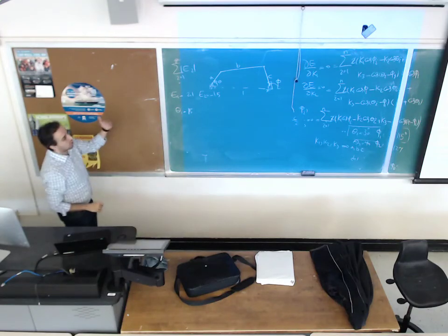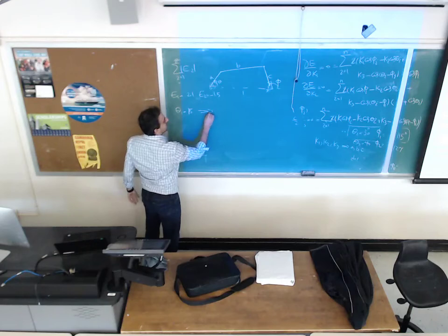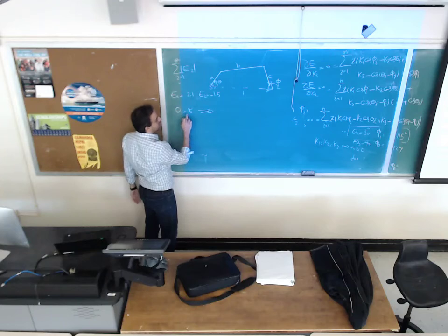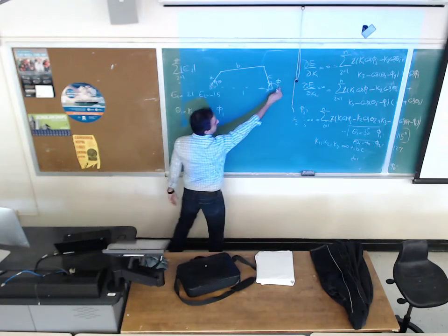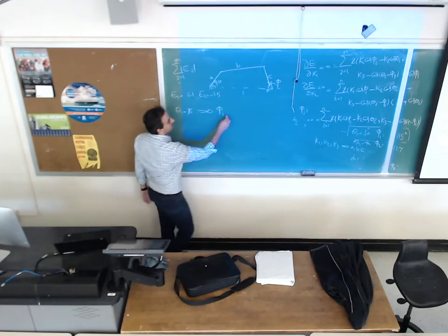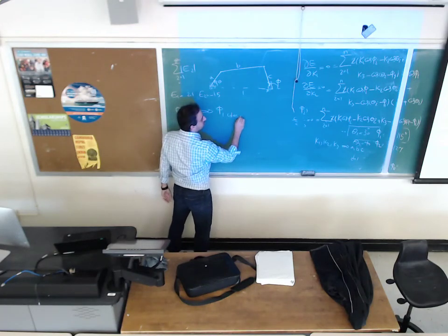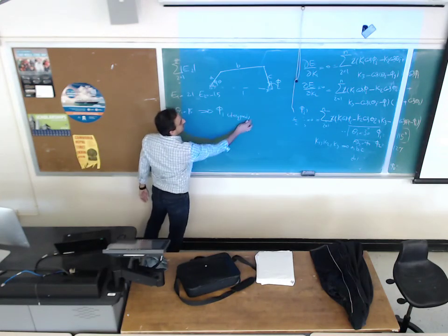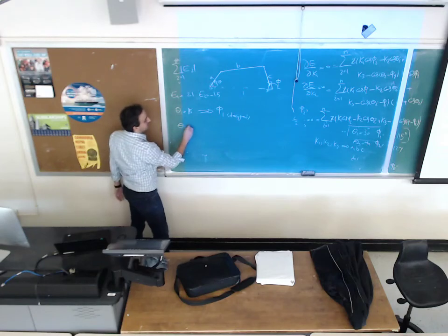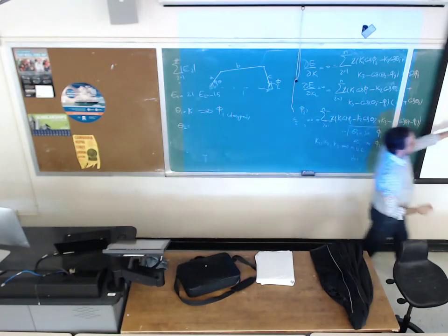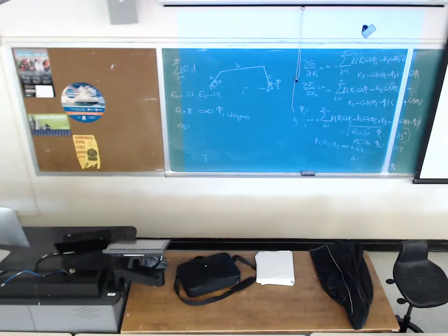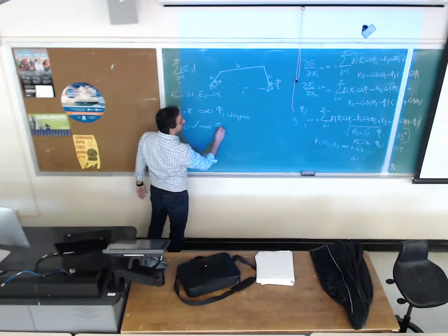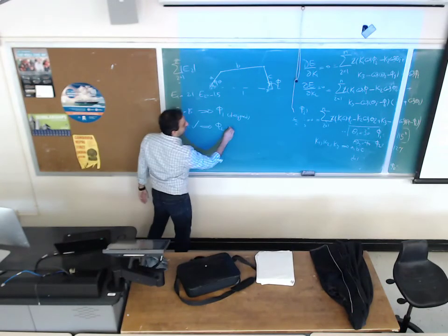You go to homework 4 or 5, the code that you have written for a 4-bar mechanism. You plug in input angle theta 1, 15, and you will find phi 1, the output angle corresponding to this, and we call it design. So you design this mechanism. For this theta, it's going to generate this phi 1 for you. Do the same thing for theta 2. Theta 2 is 15 plus theta 1, 2, whatever the value for theta 1, 2 is. For that one also you find phi 2 by using the MATLAB code that you have designed.